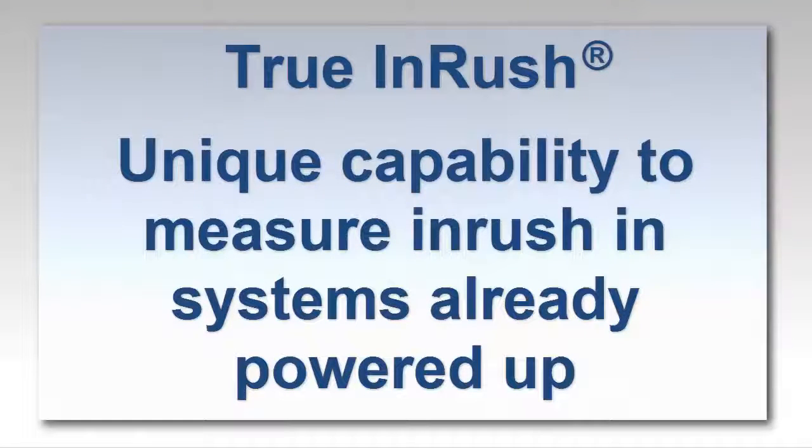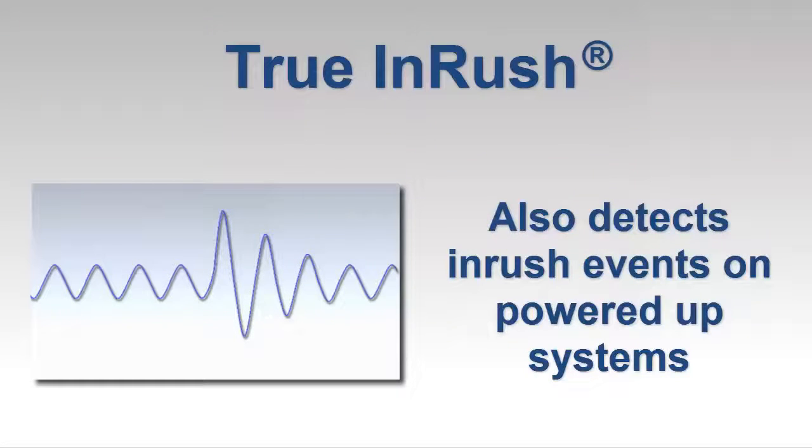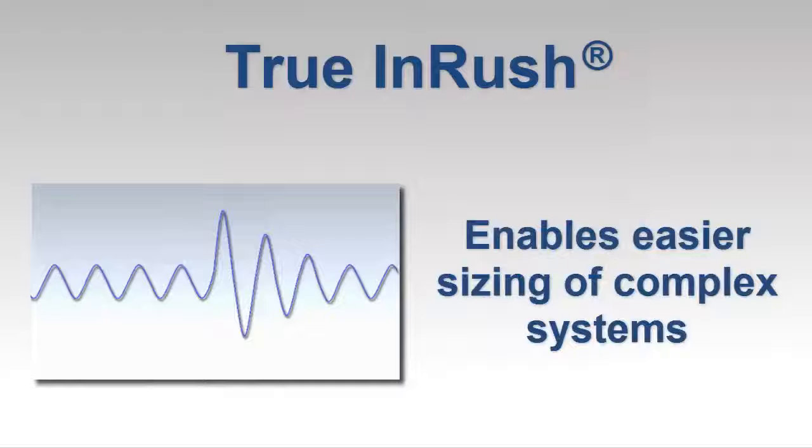AEMC's true Inrush function adds the unique ability to measure power-up events from devices on a network that is already energized. In addition to the initial power-up event, true Inrush can also detect subsequent power-up inrush events that meet user-defined threshold criteria. True Inrush captures these overcurrents, making it simpler and easier to size complex installations correctly.